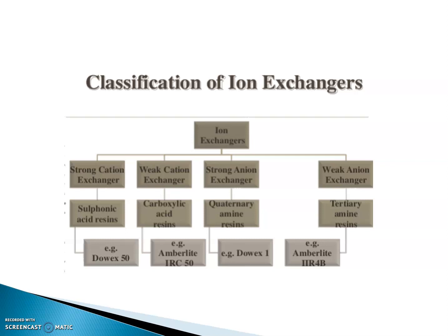Weak cation exchange resins derive their exchange activity from the carboxylic acid group, that is nothing but COOH. When operated in the hydrogen form, weak acid cation resins remove cations that are associated with alkalinity, producing carbonic acid. Weak acid cation resins are used primarily for softening and dealkalization of high hardness, high alkalinity waters, frequently in conjunction with a strong acid cation sodium cycle polishing system.